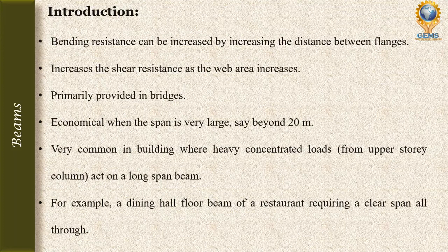These plate girders are primarily provided in bridges. You will see in the bridges we will have the plate girders. Mostly these plate girders will be used in the bridges. Plate girders are economical when the section is very large. If you are going to fabricate very large sections, plate girders are very economical, say beyond 20 meters.